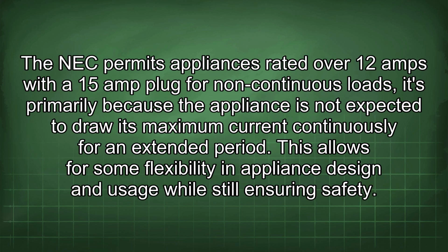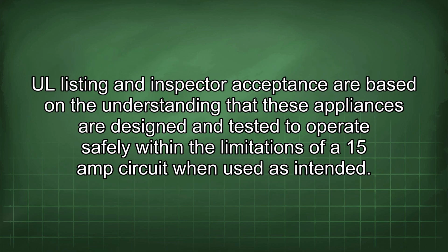The NEC permits appliances rated over 12 amps with a 15 amp plug for non-continuous loads. It's primarily because the appliance is not expected to draw its maximum current continuously for an extended period. This allows for some flexibility in appliance design and usage while still ensuring safety. UL listing and inspector acceptance are based on the understanding that these appliances are designed and tested to operate safely within the limitations of a 15 amp circuit when used as intended.